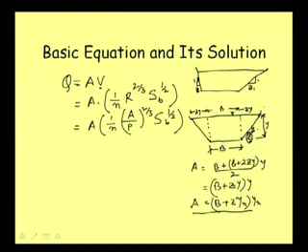And that will also depend on the type of soil when we are cutting a man-made canal. Suppose it is very rocky terrain and we are making a channel through it, then the side slope we can make is almost vertical, because if we cut a vertical slope in rock, there is no chance of failure. But in alluvial soil, if we make a vertical cut, it will definitely fail, so there is no meaning in making that.